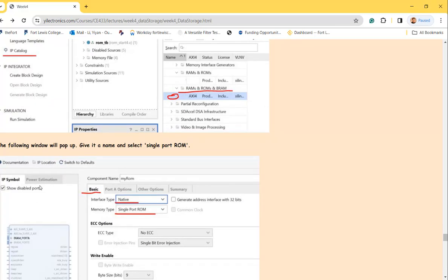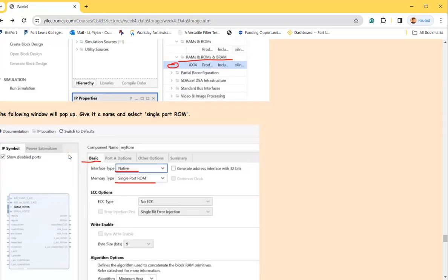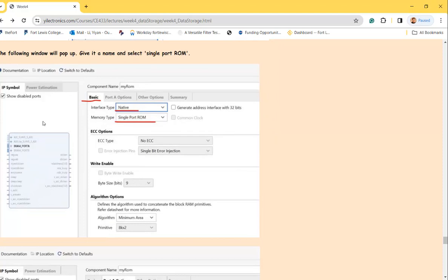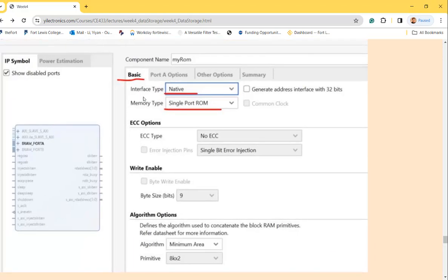There's one more thing that is new in this tutorial. You can definitely create a ROM file, the Verilog module by yourself, but also they have IP cores. I think this is really exciting because this is the first time we are using an IP core in the design EDA tool, which is Vivado. It provides a lot of IP cells, especially memory IPs, all different kinds. You can create the IP using the wizard here. Following all the steps, it's going to create a memory chip for you.